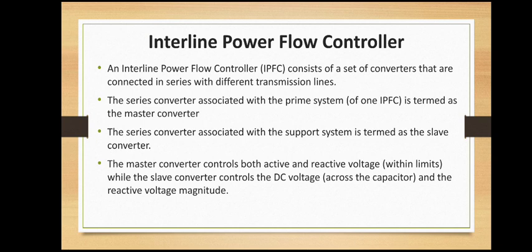Interline power flow controller. An interline power flow controller consists of a set of converters that are connected in series with different transmission lines. The objective of this controller is to address the problem of compensating a number of transmission lines connected at a substation.